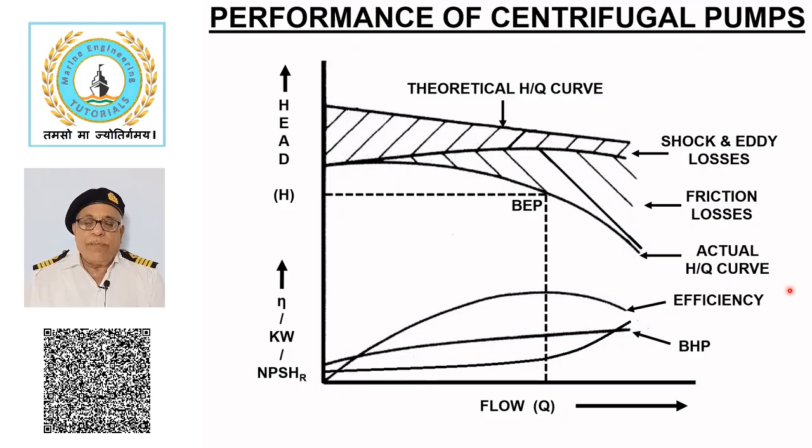Starting the pump with the discharge valve closed also helps to prevent damage to the discharge line in case the pump is already primed, as the pressure surge thus generated can create a shock wave in the delivery line, resulting in rupture of the weak section.